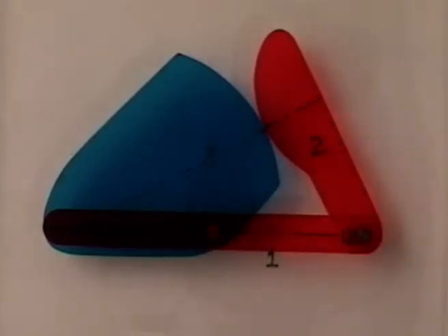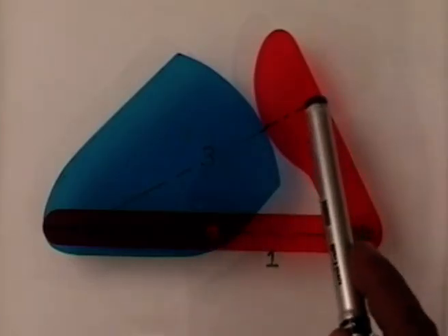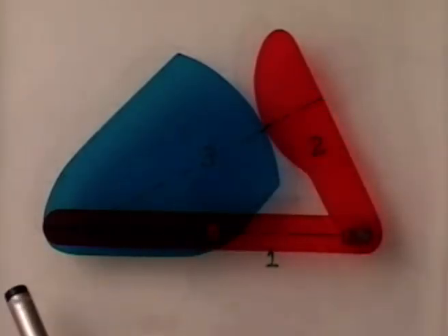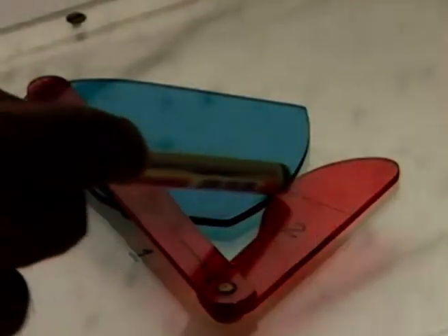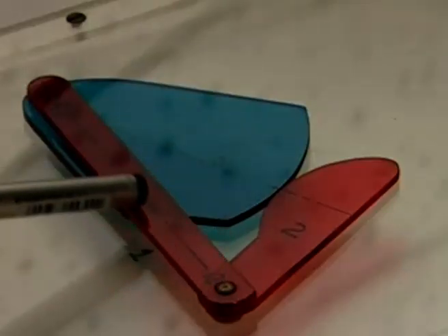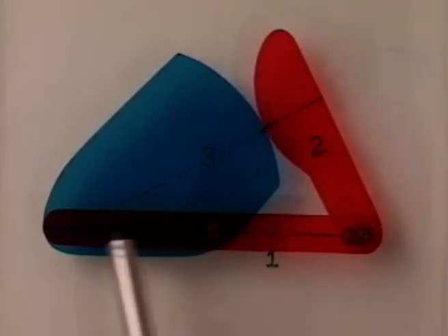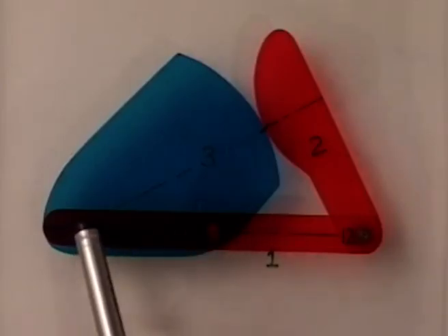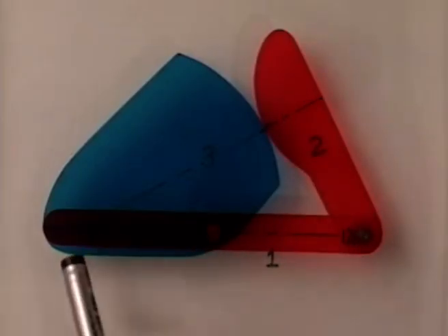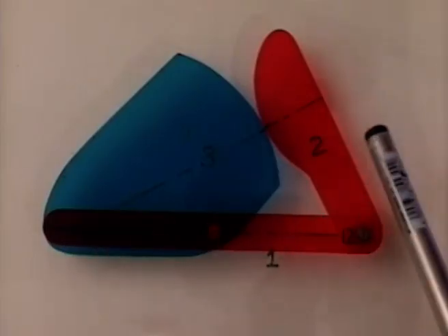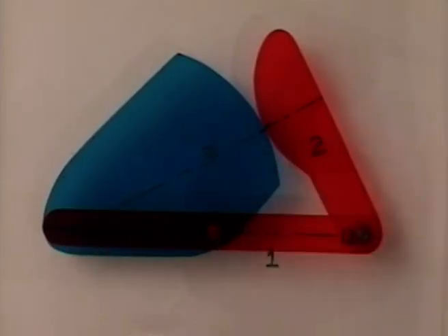And we also know from the Aronhold-Kennedy theorem that 1, 2, 1, 3 and 2, 3 must be collinear. That is how we determine the location of 2, 3 at the intersection of this common normal and this line joining 1, 2 and 1, 3. 1, 2, 1, 3 and 2, 3 must be collinear and 2, 3 must lie on this common normal. That determines this location 2, 3. So this is the relative instantaneous center 2, 3 between two moving bodies 2 and 3.